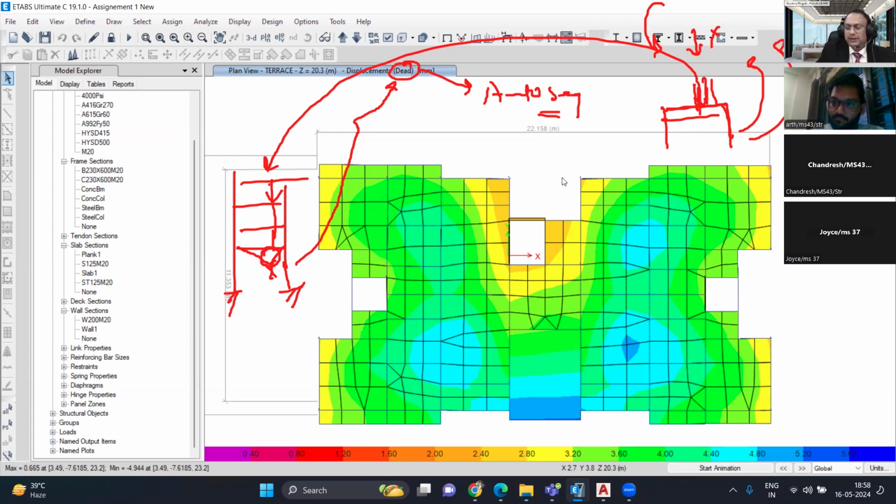Let's say, for example, this is a building. You are not actually manufacturing the building and bringing it in. What is the analysis, show me. No, it's not happening that way. Yes, but sir, you are modeling in that way, which is insane. So you need to model it the way it is getting constructed, floor by floor, brick by brick. That's why such type of analysis is required. You are basically mimicking the same parameters and same sequence, the way it is happening.